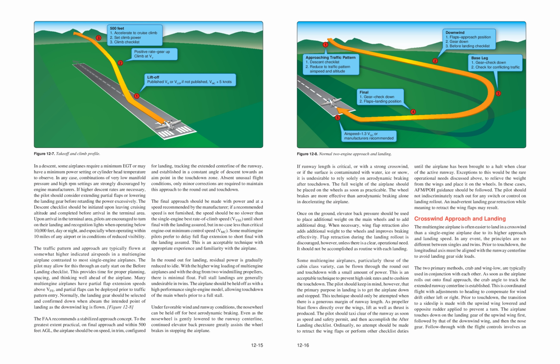Exceptions to this would be the rare operational needs discussed above, to relieve the weight from the wings and place it on the wheels. In these cases, AFM/POH guidance should be followed. The pilot should not indiscriminately reach out for any switch or control on landing rollout.